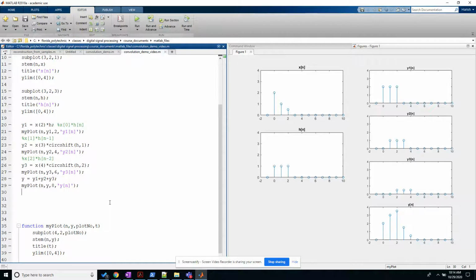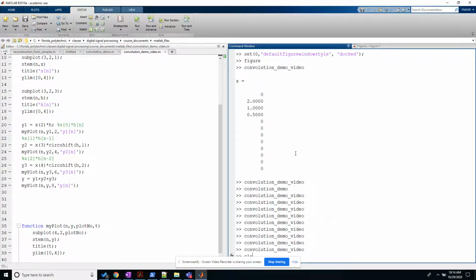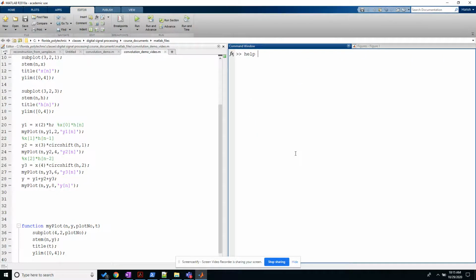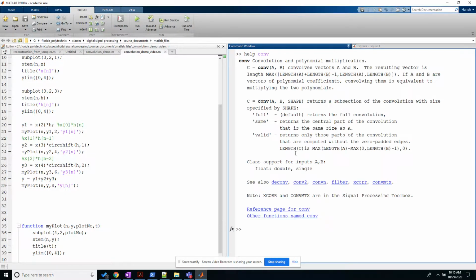So next, let's verify our calculations. At this point we did it two ways, by hand and by using Matlab, where we computed individual signals and took the sum. So we just verified that our calculations are consistent, but we also want to match this with some external third-party calculation and see if it matches that too. Matlab has a function called convolution. So let's do this using Matlab's inbuilt function and see if we get the same results. Matlab has a function called conv, which calculates the convolution of two signals.